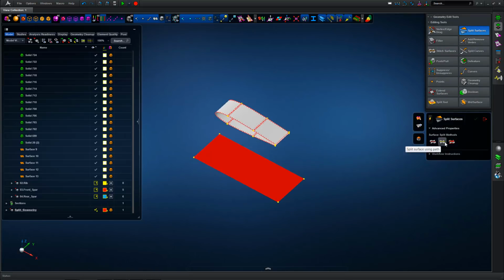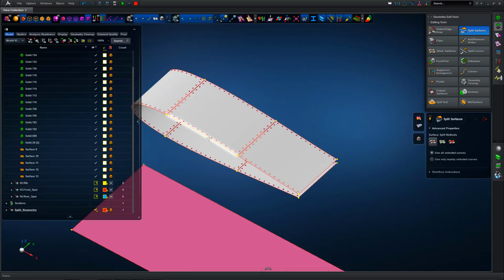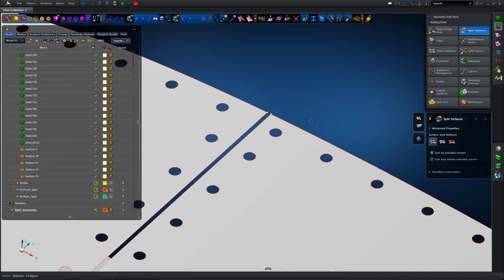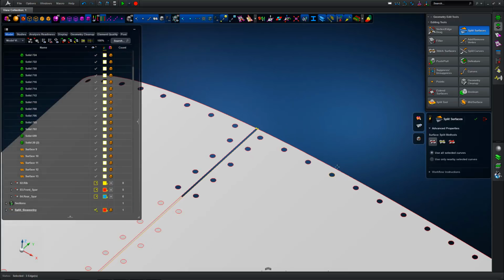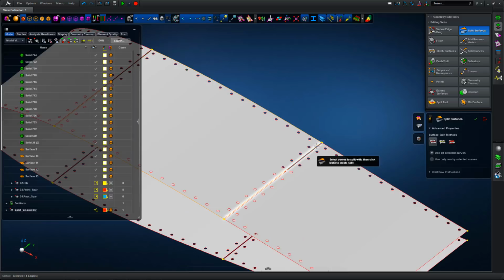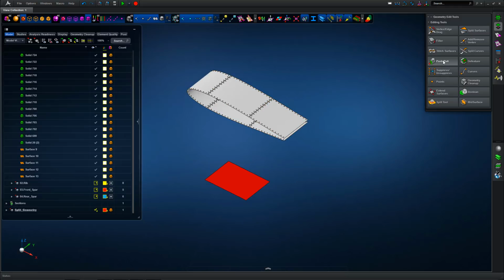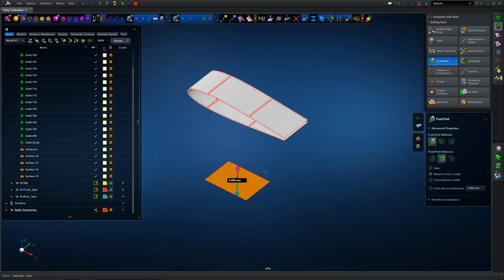So once we have a sketch surface defined sort of normal to the bottom of the wing, we simply pick the edges of one particular panel of interest. So we're just selecting the surface, selecting the edge. Once we've got those defined, it's simply a middle mouse button to accept, and we can see when we maximize the view that we have a single surface left behind that's cut, which is effectively a projection of the edges of the wing surface projected onto the sketch surface.